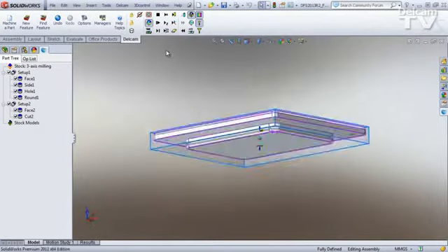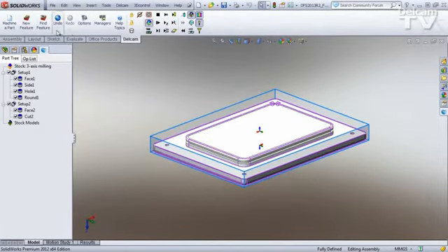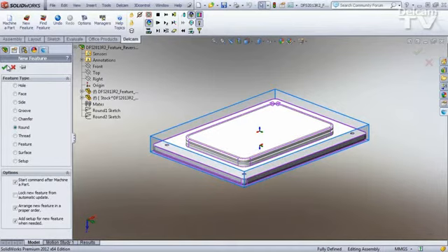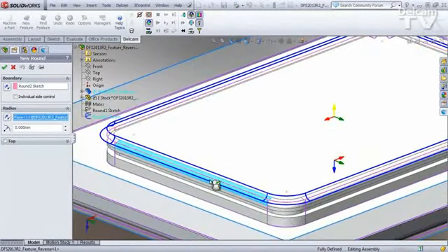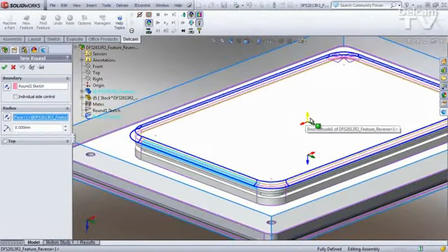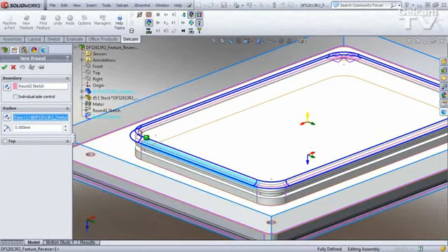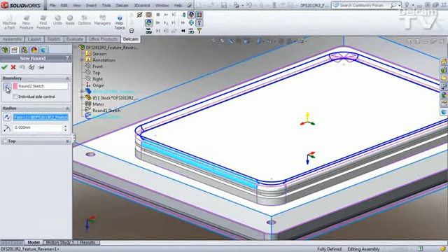Now let's look at the back side. Go over to side 2. Another round feature, the second sketch. The radius is that face right there. Immediately you can see a problem with the machining direction, the cut direction. It's coming from the wrong direction. You can see the radius is actually inverted, it's upside down. It's cutting the wrong side too, so I'll flip the machining side.